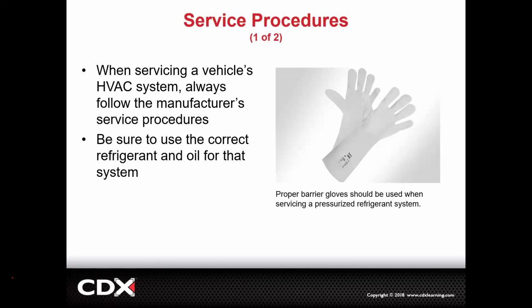A mechanics glove is not going to protect you against half the chemicals, the oil, the coolant, the refrigerant. They're not really mechanics gloves. If you're working with refrigerant, you need a glove that's impermeable. It's a barrier glove. This would be the glove to use. The refrigerant can't get on your skin and cause that frostbite. Cool. That's a barrier glove. These ones are nicer and longer sleeve and a lot thicker than the nitrile gloves we commonly use.